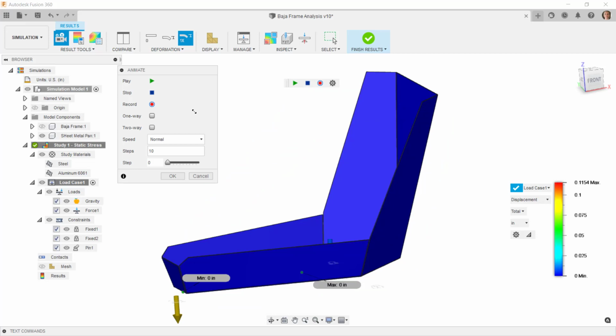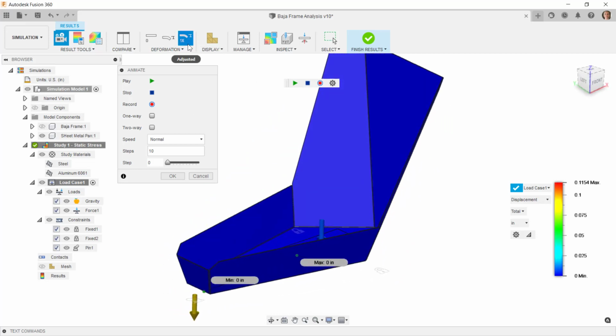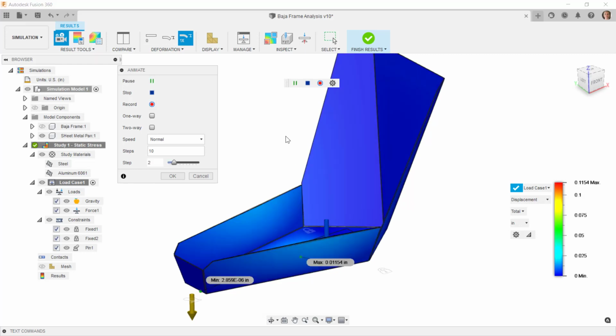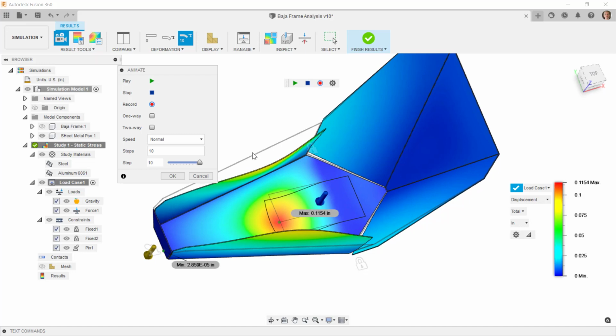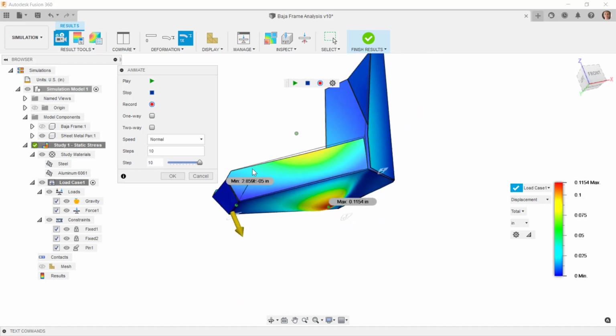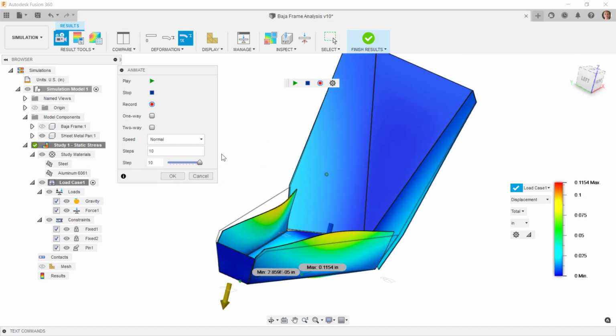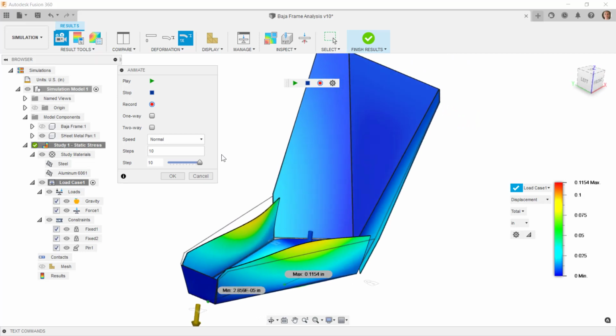Let's go to the sheet metal, and I'll exaggerate that, and I'll play that so we can see how that sheet metal moves. So if this isn't bonded over here, it's going to pull that towards the inside and then push it down here in the center if we don't put another beam down here. So at least you could use that to make some early initial starts on making changes. And we probably weld these edges across over here as well, bond those together.